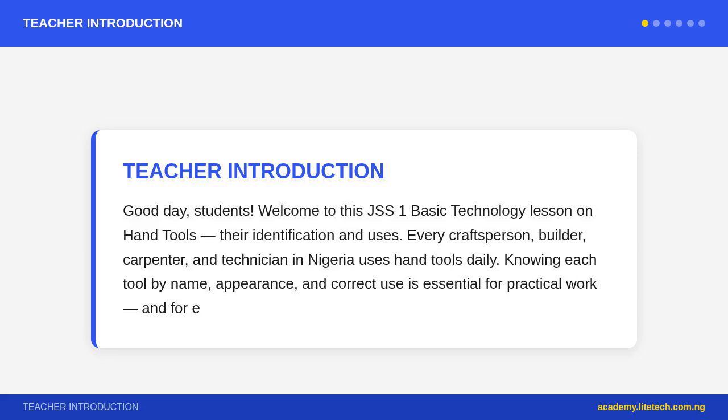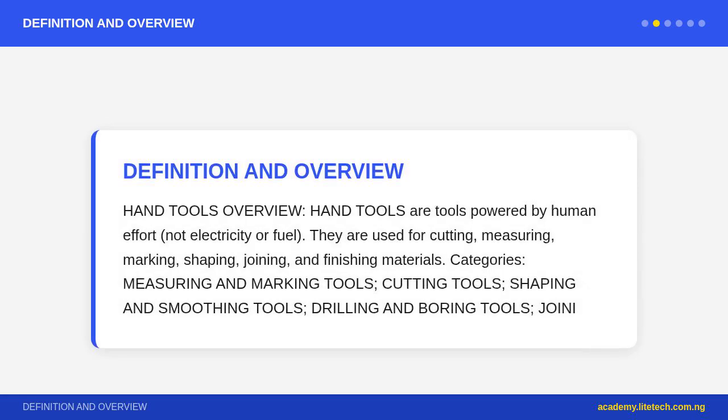Tri-square, or set square, an L-shaped tool used to check and mark right angles, 90 degrees, on wood or metal. The stock and handle is placed against the edge of the work, and the blade lies across the face. Marking gauge, a wooden or metal tool, marks a line parallel to an edge of wood for joints, tenons, and mortises. An adjustable spur scratches the line.